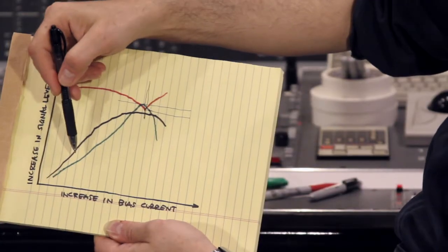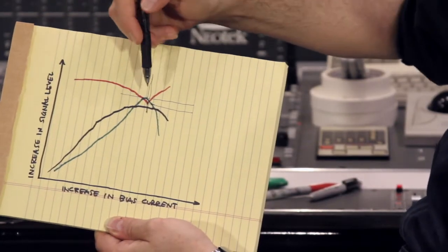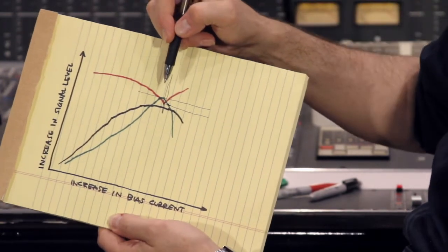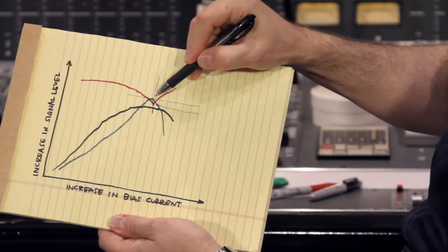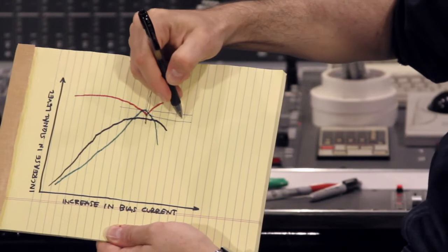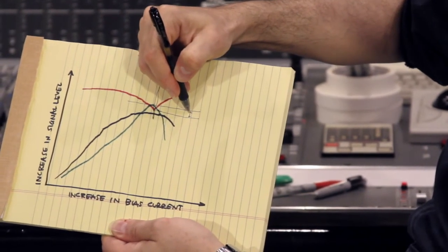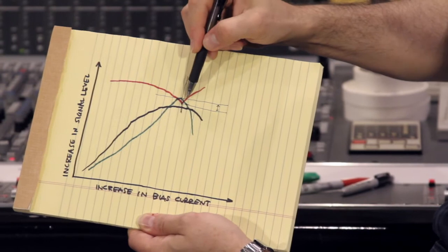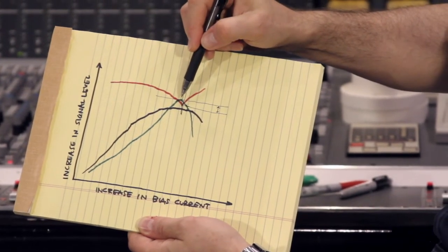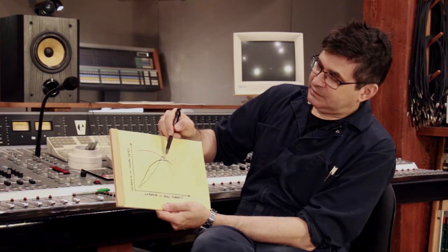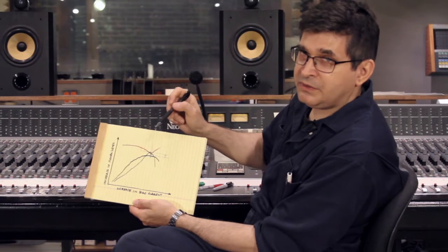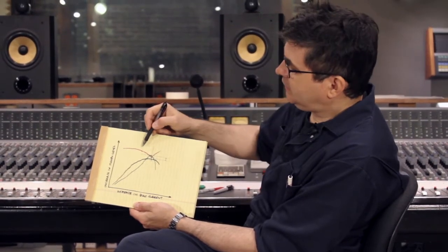And that can be described in terms of decibels. That is, you increase the bias on the machine until you find the peak sensitivity at a known frequency, say 10 kilohertz or 20 kilohertz. And then you increase the bias until it drops by this amount, and you will have found the bias point of minimum noise and distortion. And that's the critical bias or optimum bias for your tape machine. That point is going to be different depending on the geometry of the heads, that is the width of the head gap on the heads, and the formulation of the tape.